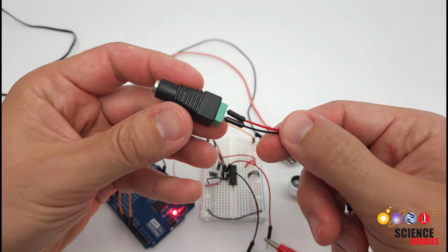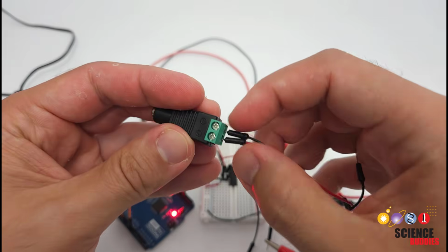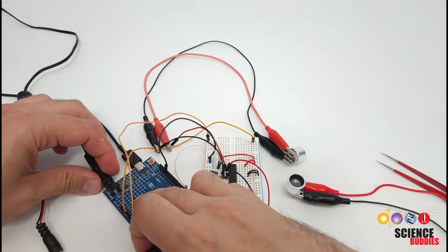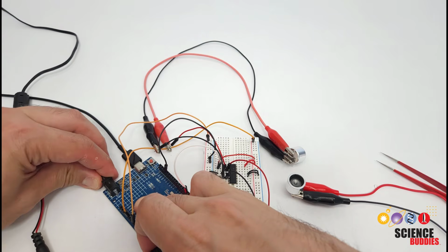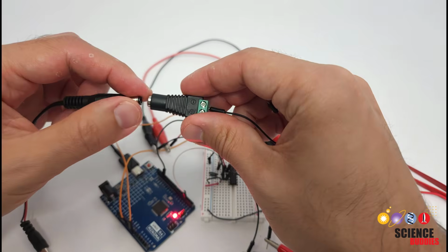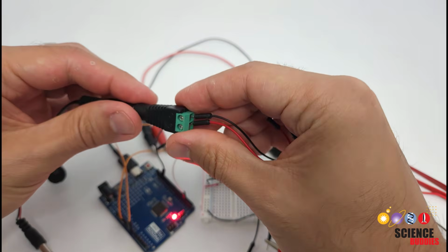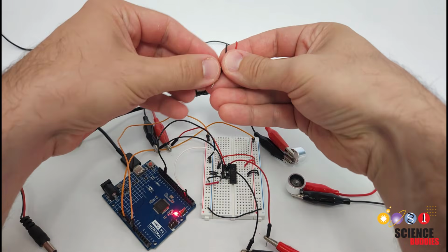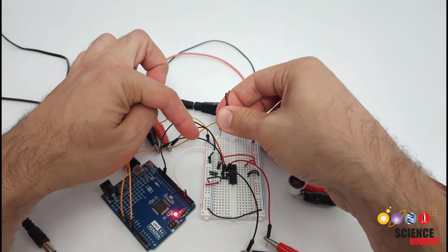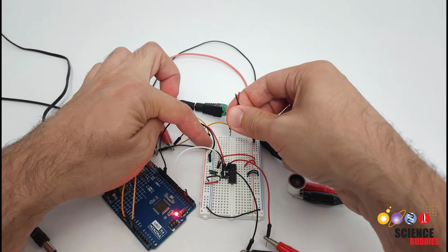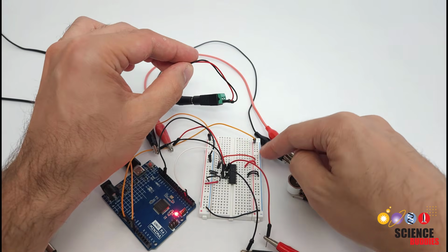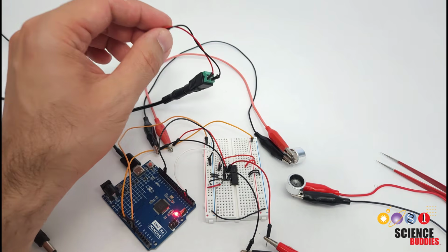Instead, you can get one of these little adapters that has screw terminals that you can connect jumper wires to, and instead of plugging into the Arduino, you can still power your Arduino separately with the USB cable, and then you're going to plug your wall adapter into this adapter, and then plug both the power and ground connections from that adapter into the power and ground rails of your breadboard, again on the side that you had left open previously, not on the side that's connected to 5 volts from the Arduino.